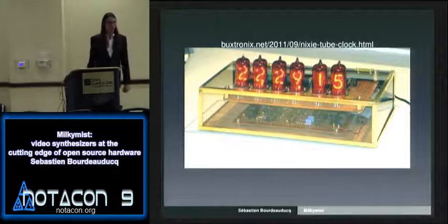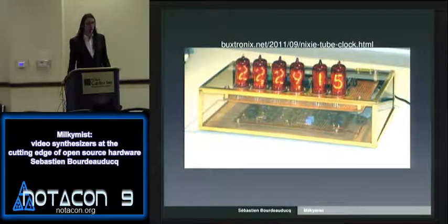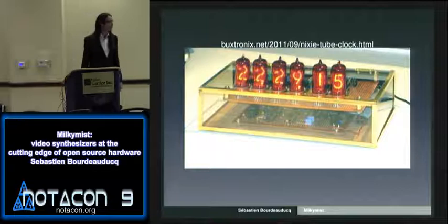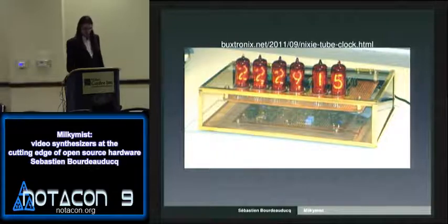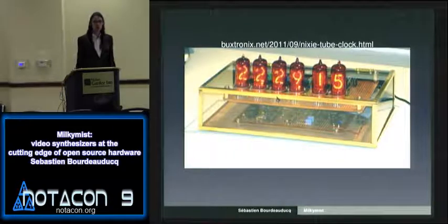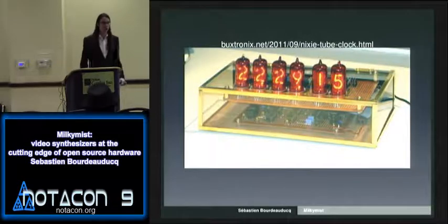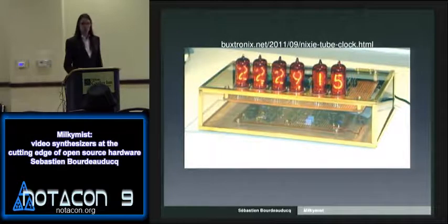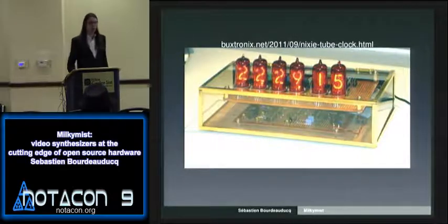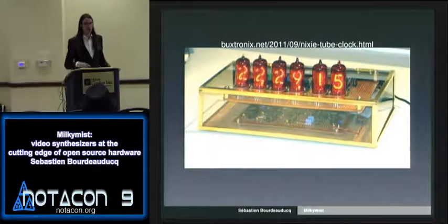I think this might be something that you know about, the Nixie clock. It's a very popular project for people who do electronics. And this Nixie clock is actually not using a microcontroller. A lot of people these days use AVRs for Nixie clocks because AVRs have become really cheap and very powerful. But this one particular one didn't use any microcontroller. Instead, it uses basic logic gates, which you see here. They are CMOS or TTL logic gates. And all the functionality of the Nixie clock is just implemented with logic gates and flip-flops.